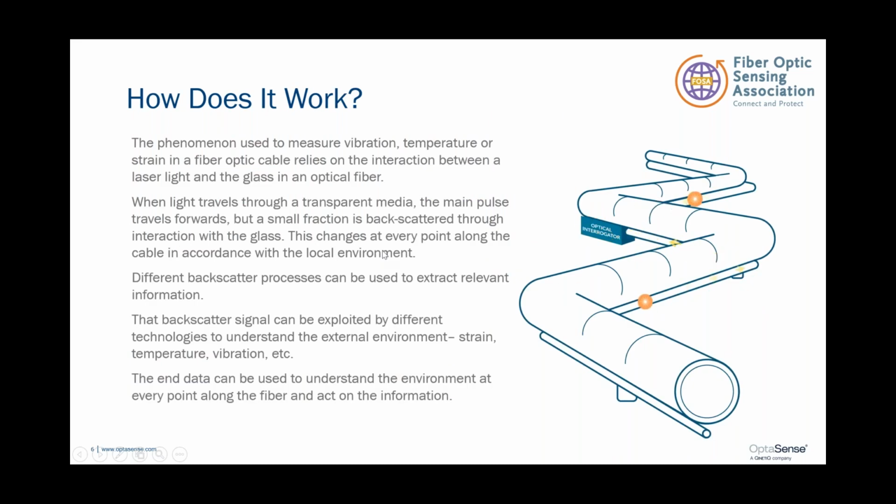This illustrates the typical methodology. We fire a short pulse of light from a coherent laser down that single core that we may be adopting. We may have borrowed it from a cable that is there for communication purposes. And we look at the backscatter signal, that is the echo from the glass itself. We can pick up the acoustic field from very low DC frequencies up to kilohertz frequencies, and we can process that to look for the sounds of, or the feel of, different behavior that is taking place.